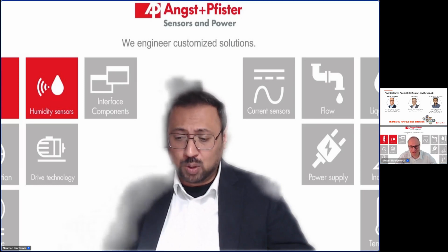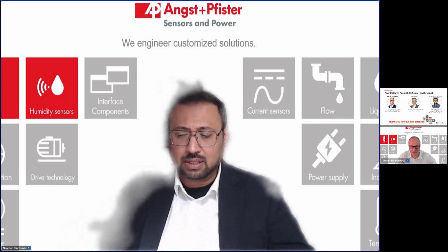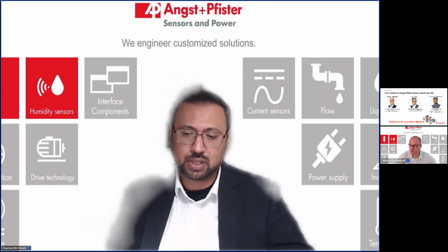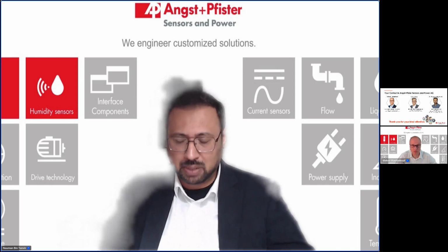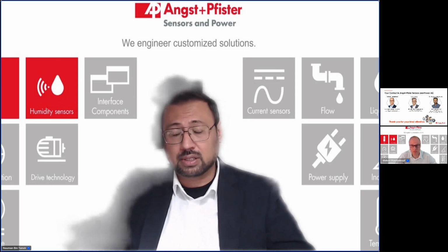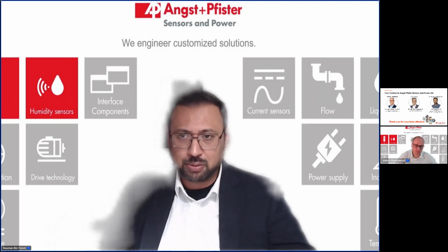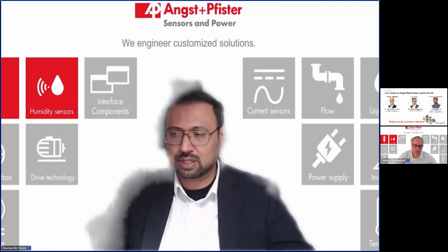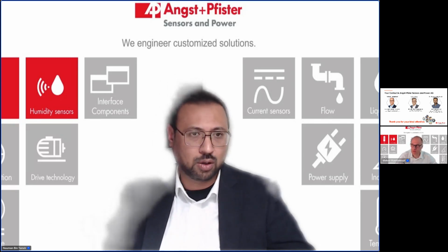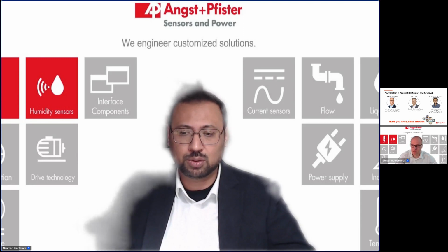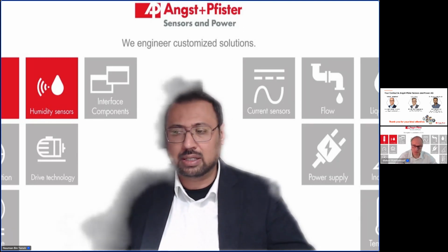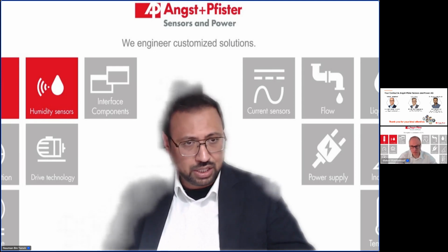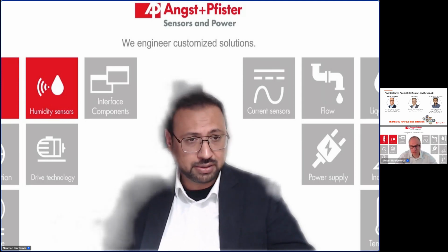Yes, all three of them, amperometric, potentiometric, and paramagnetic, do not have consumable parts. This is not entirely true for the amperometric. Nonetheless, we have tested the sensor with a very long lifetime. In comparison to a typical electrochemical sensor, the sensor can operate under certain conditions easily up to 10 years.